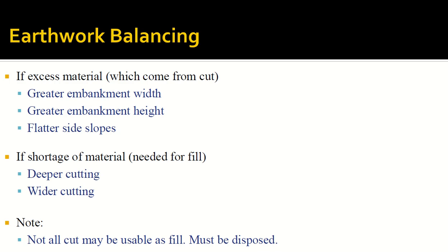Okay, but in both cases, we are making the side slope what? Flatter. Because flatter side slope will give you more strength, better stability. Clear? Okay. Whether you have extra material or you don't have extra material, whether the project is balanced or not balanced on paper.